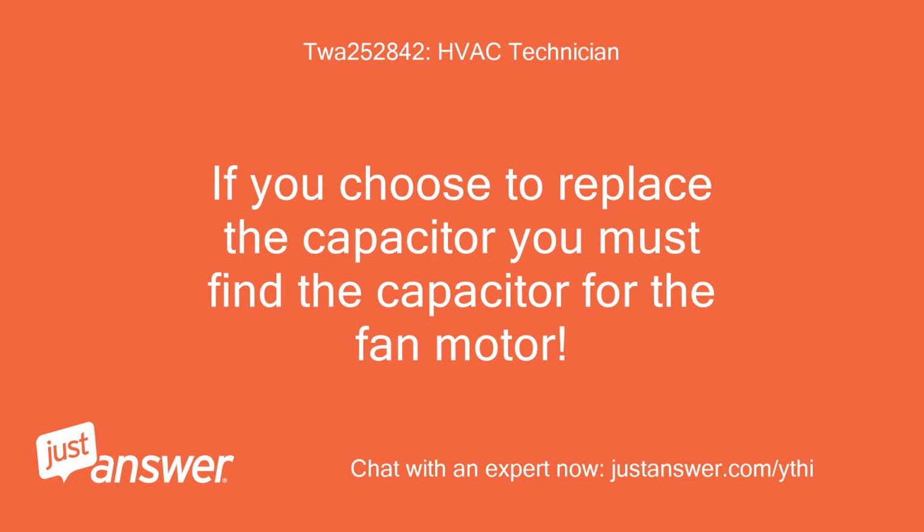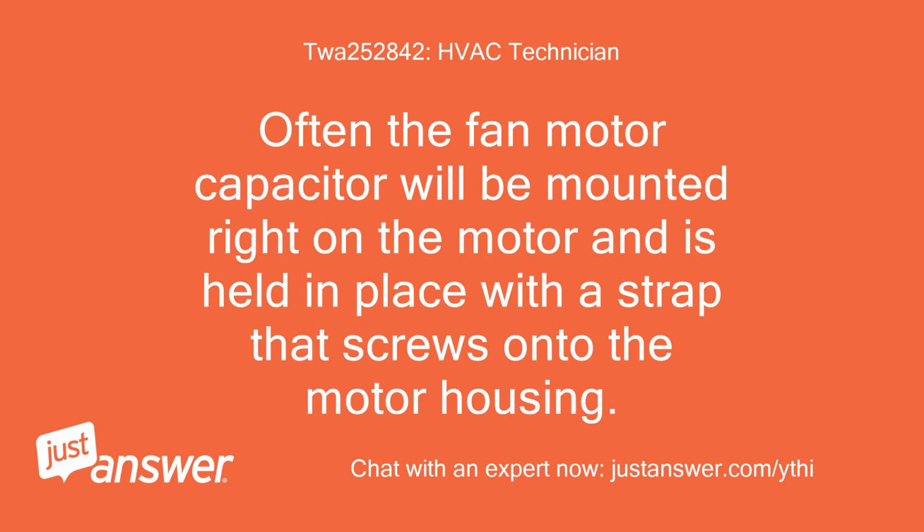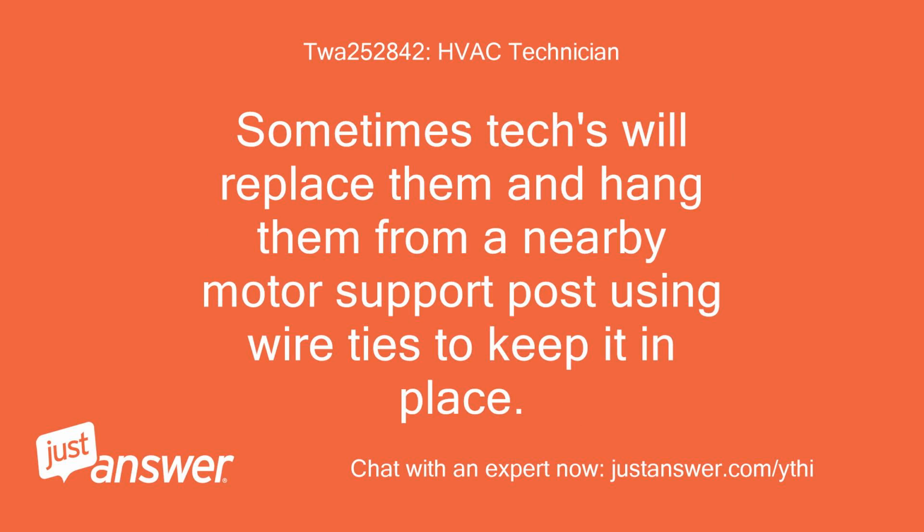If you choose to replace the capacitor, you must find the capacitor for the fan motor. Often the fan motor capacitor will be mounted right on the motor and is held in place with a strap that screws onto the motor housing. Sometimes techs will replace them and hang them from a nearby motor support post using wire ties to keep it in place.